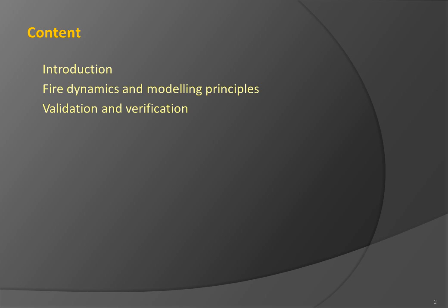In the validation and verification section, I will quickly present quality criteria associated with CFD simulations and specifically with fire modeling. Generic best practice principles will also be discussed. We will review different aspects of general and specialized CFD simulation tools, including geometry resolution, grid generation techniques, turbulence, reaction, and thermal radiation modeling.